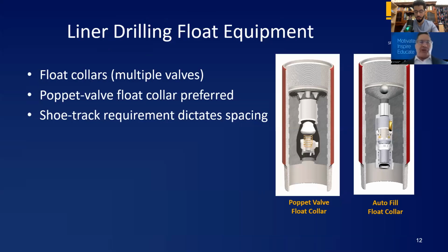Let's talk about liner drilling float equipment. We recommend poppet type float collars. In other words, dart type float collars with a spring mechanism right here versus the autofill type. Now, why do we recommend this? With poppets, they're a lot stronger. We've seen fewer failures with these than with autofill.